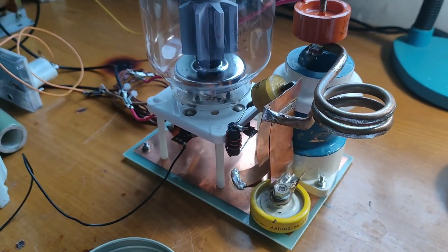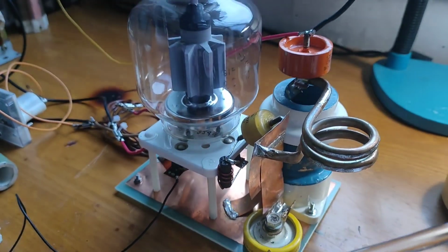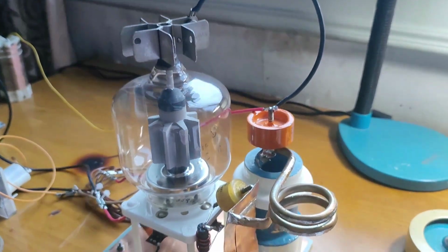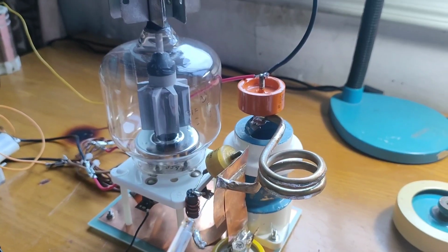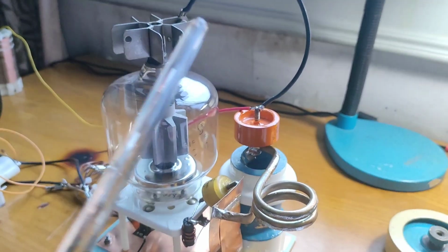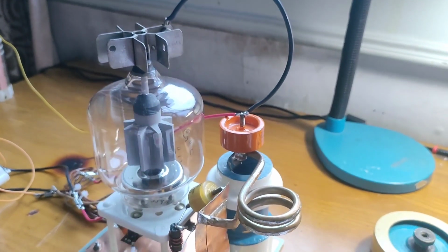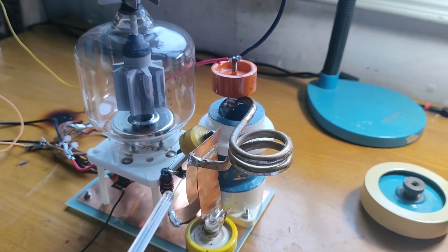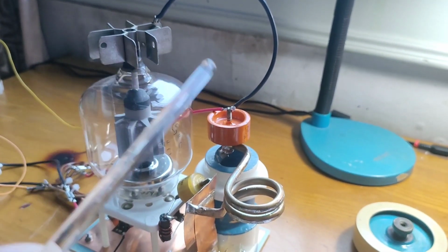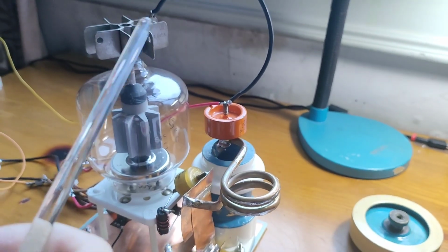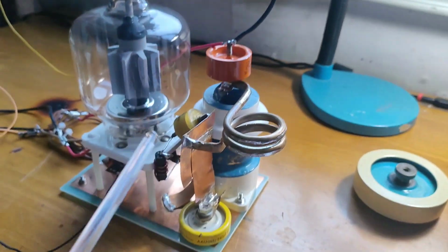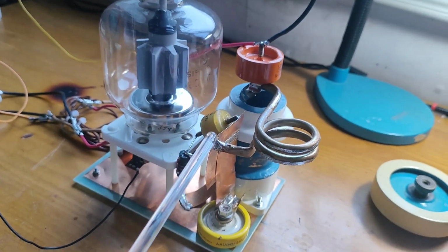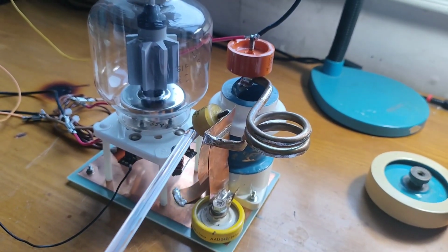The next thing I will tell you is how to kill the parasitic oscillation. Sometimes in a vacuum tube linear amplifier, I mean for the HF band, they simply add a choke which is mounted onto a low resistance resistor and connect it between the anode and the output pi network. That can kill the parasitic oscillation. And here I simply use the same method, but connect it in the grid loop.